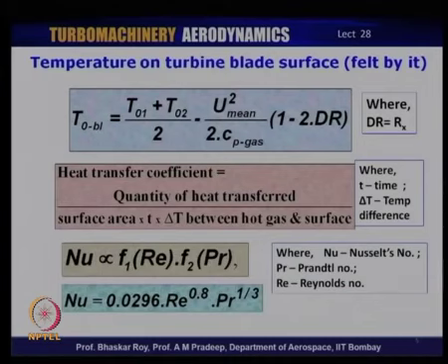Now, when we talk about turbine cooling, the first thing that comes to mind is what are you cooling? You see, the turbine is processing gas which is hot and of course, high pressure, but the blade feels a temperature. The feeling of the blade here is the important issue. The blade feels a temperature which is not the same as the turbine entry temperature. So, if the turbine entry temperature is T01 and the blade exit temperature is T02, what the blade would feel is an average of the two minus the rotating kinetic head, which is shown as u mean square by twice Cp of the gas which is passing through, plus the degree of reaction factored in here.